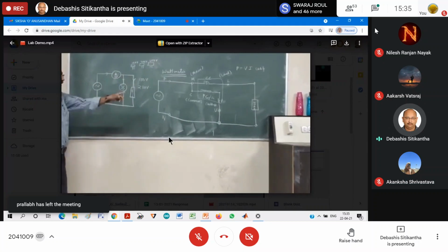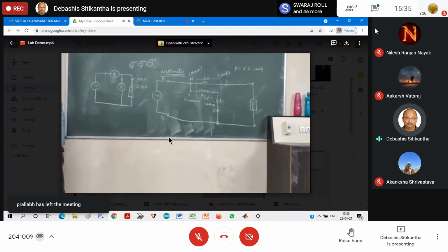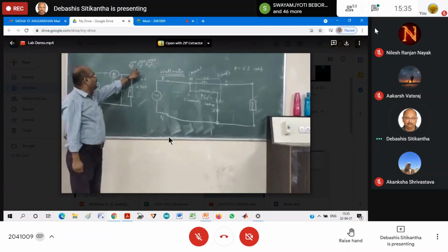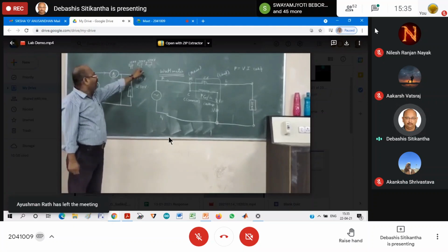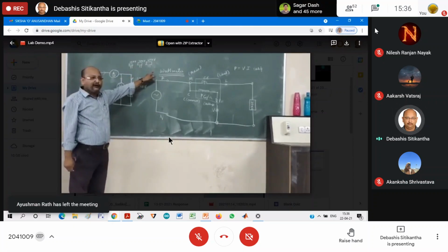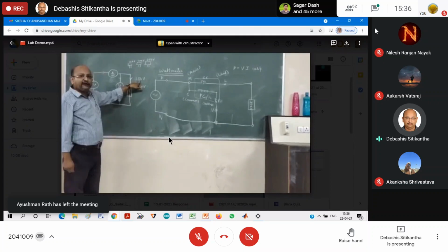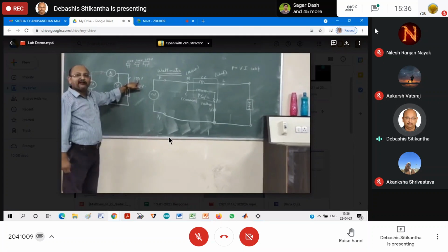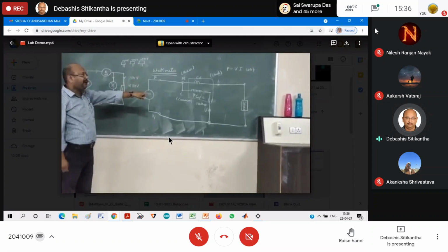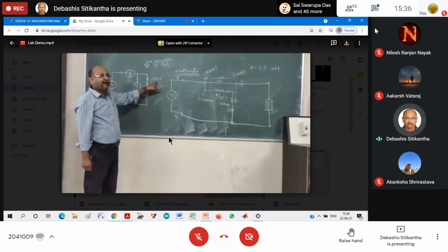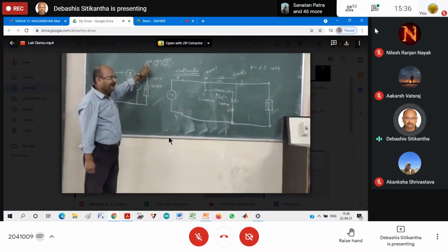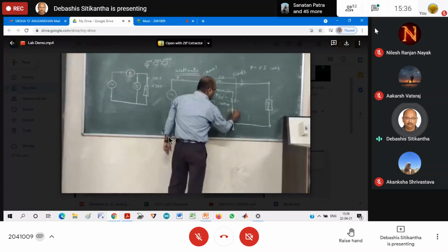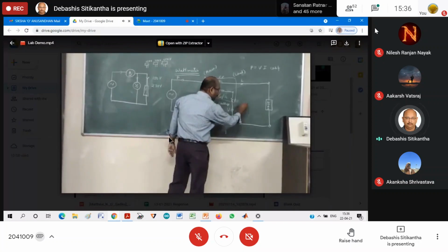That means you can find the power consumed by the load at a maximum of 150 volt, 300 volt, or 600 volt. So in this case, I have to measure the power consumed by that particular load at a supply of 100 volt, so obviously I will choose this 150 volt.